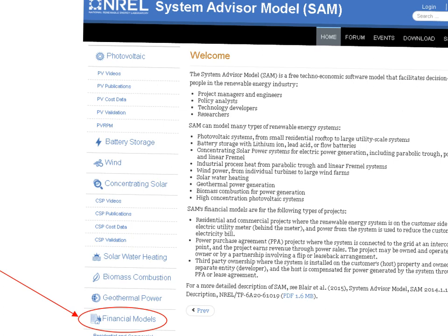So for example, I was looking at a project, just sort of a fun project, to see what it would be to put a 2 megawatt PV array on campus someplace. You can actually specify a location, and it pulls data from the NREL database based on the solar insolation data, and it'll tell you how many megawatt or kilowatt hours you would be expected to produce based on month. So it actually will spit out that data for you. And if that's photovoltaic, you can do wind.